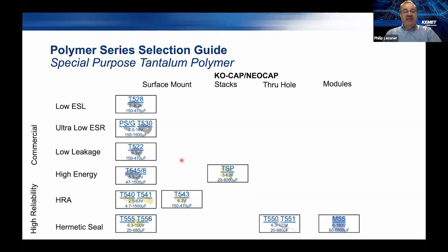applications like the SSD backup, energy backup application that I mentioned, and also this TSP series, which is a stacked series, stacking of several cases on each other in a surface mount configuration, which is found use in some of those RF pulse applications and radar applications that I mentioned.